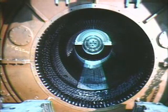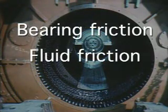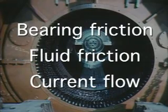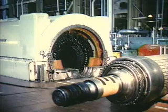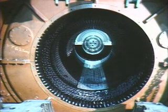Inside a generator, several factors can contribute to the creation of heat. These include bearing friction and fluid friction. But the greatest source of heat in a generator is current flow. Most of the parts inside a generator can withstand only a certain amount of heat. Above 250 degrees Fahrenheit, for example, most insulating materials begin to break down, which can cause electrical faults. This means that the operating temperature inside the generator must be carefully monitored and controlled.